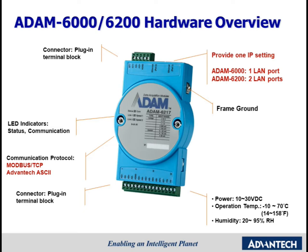Here is the hardware overview of the ADAM Ethernet module. There are two connectors, which are located at the top and the bottom of the module. The LED indicators in the middle provide information such as I/O status and communication status. The communication protocols are Modbus TCP and Advantech ASCII. On the right side, there is a frame ground screw, which is for protection.